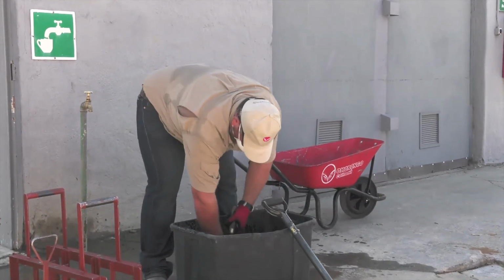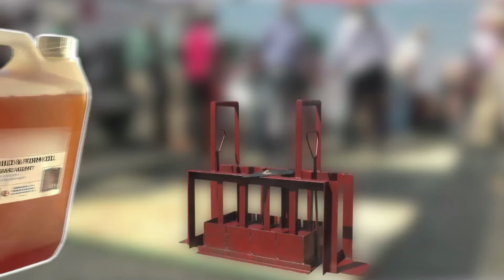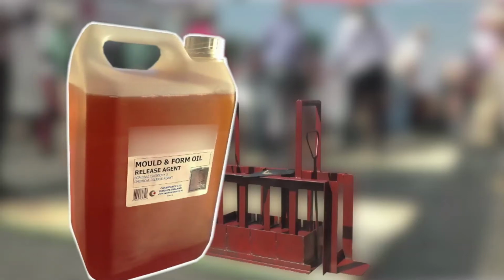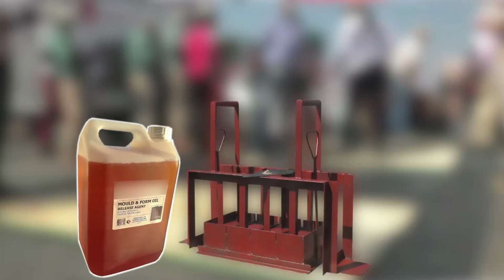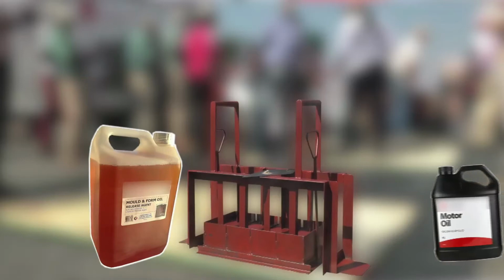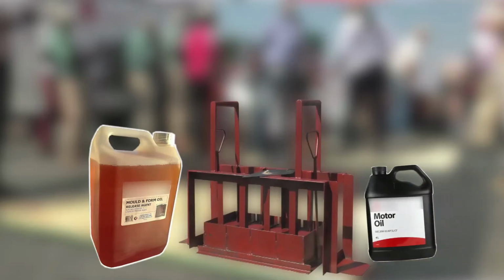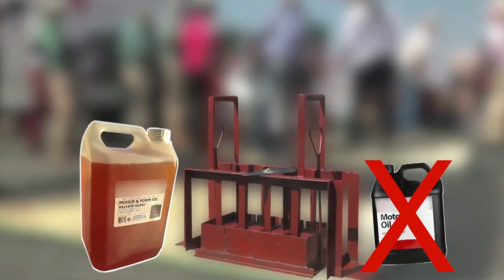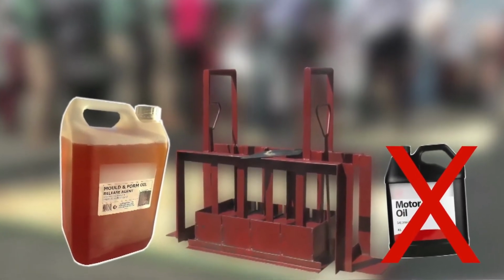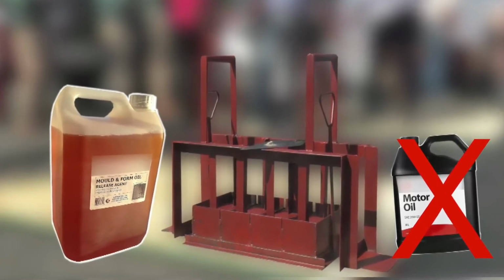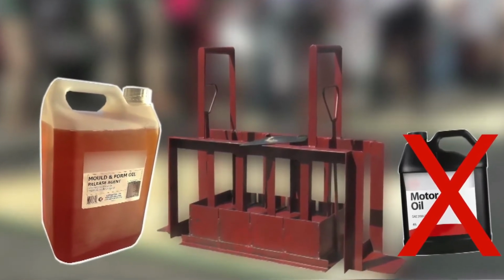Should you want to, you could use mold oil, available at any hardware store, to oil the brick mold. The purpose of this is to make demolding easier. Please do not utilize old motor vehicle oil. It will color the bricks and reduce bonding between bricks and mortar when you build a wall. If you want to, you can also oil the rest of your tools.